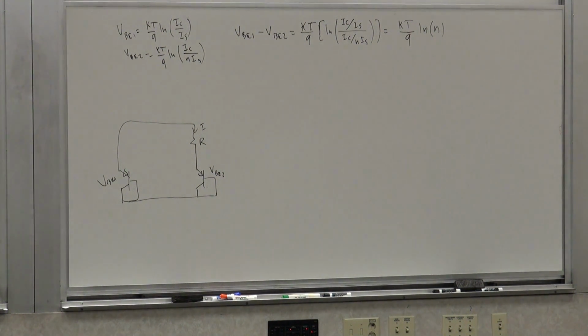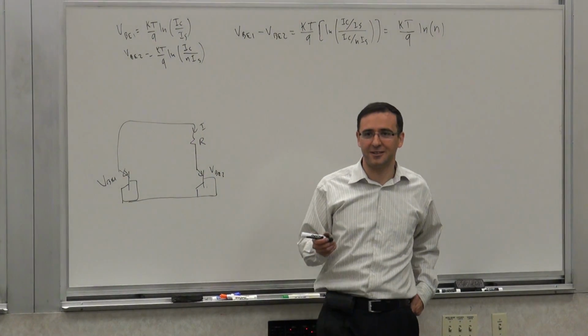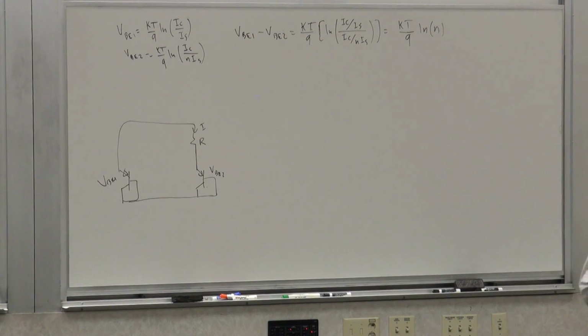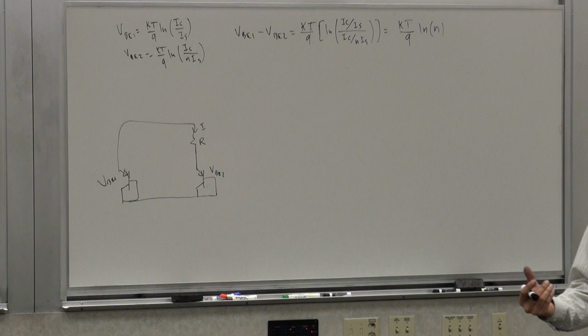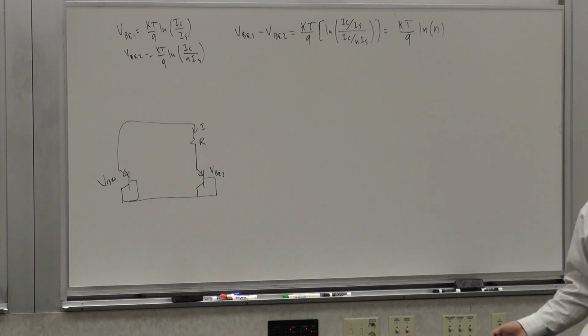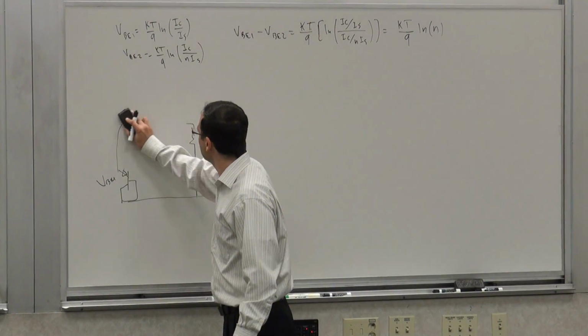It's the difference of 0 and 0 if I do it this way. But you already have the structure. I know. Because people do this, that is the reason I do it, right? People think this way. I'm just trying to tell you what is wrong in that solution. There's nothing fundamentally wrong. You do get the difference of 2 VBEs, but you get the difference of 2 zeros, which is still a 0. So you need to have a non-zero current for this to be useful. So how do you make non-zero current?